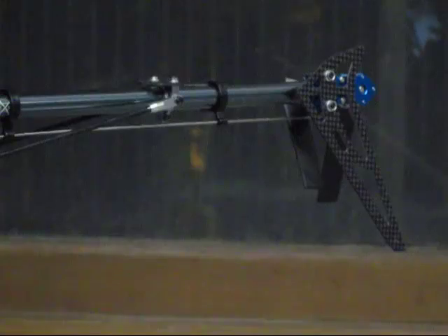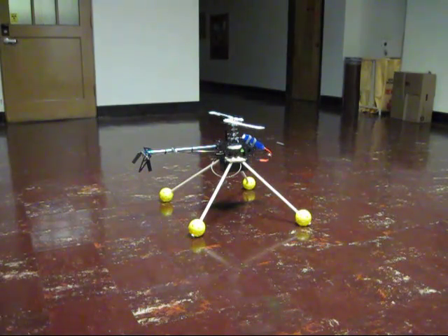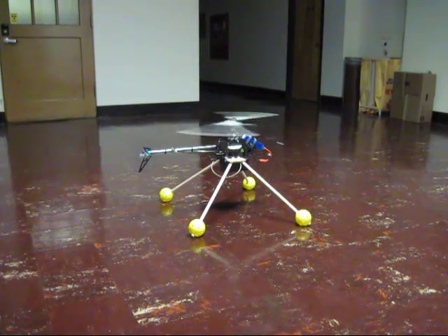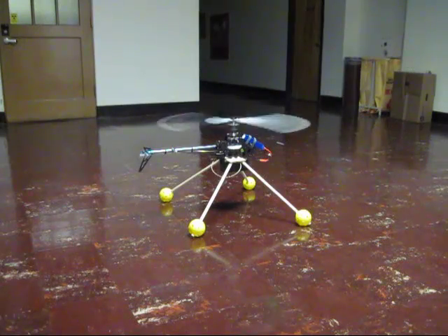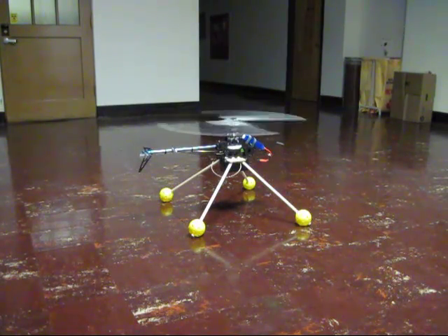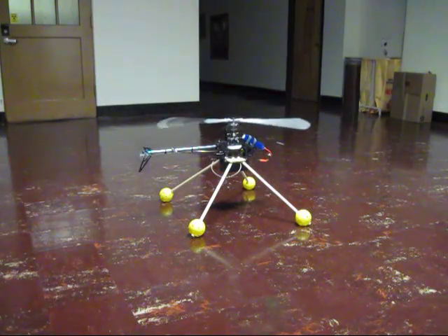So this is a test of one of our safety features. You'll actually get to see the helicopter spin up now, and then I'm going to disconnect the wireless connection, and within a second of disconnect it will power down the throttle. So we're already connected, so I can give it power. So this is actually the minimum throttle. It's not even anywhere close to taking off. Now I can disconnect, and it's powered down.